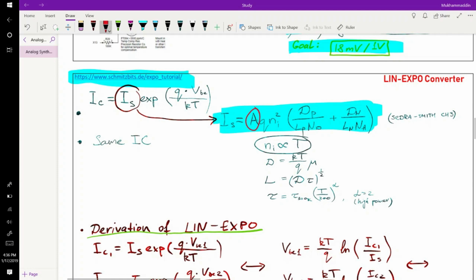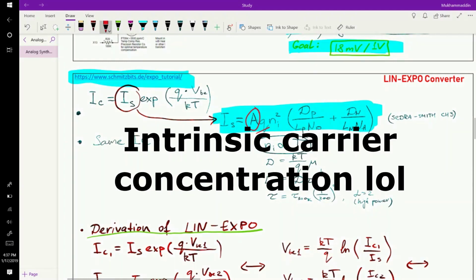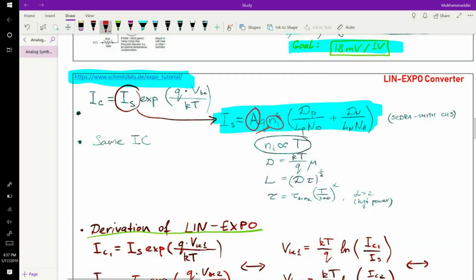So you have your cross section of the diode, you have elemental charge, you have Ni. Ni is number of intrinsic carriers in this specific material. So for silicon, it will be a certain number, and so on. And important thing about this Ni is that in this specific formula, it is squared, and it's also a very high function of temperature. Now, it is a very high function of temperature, and it's also squared on top of that.